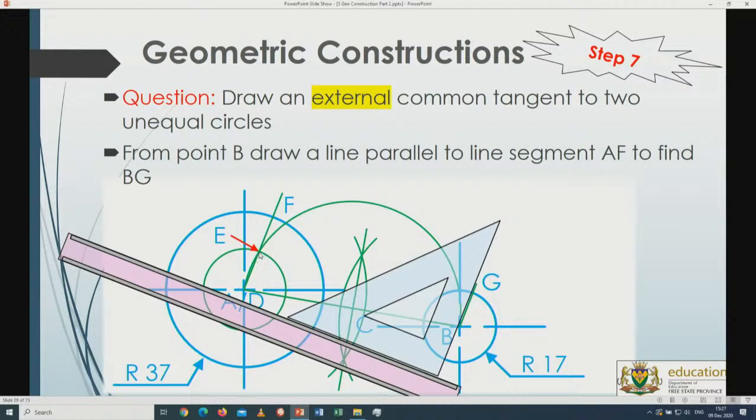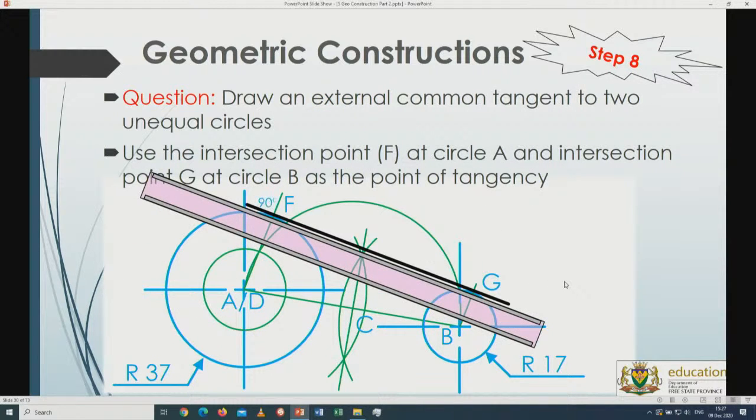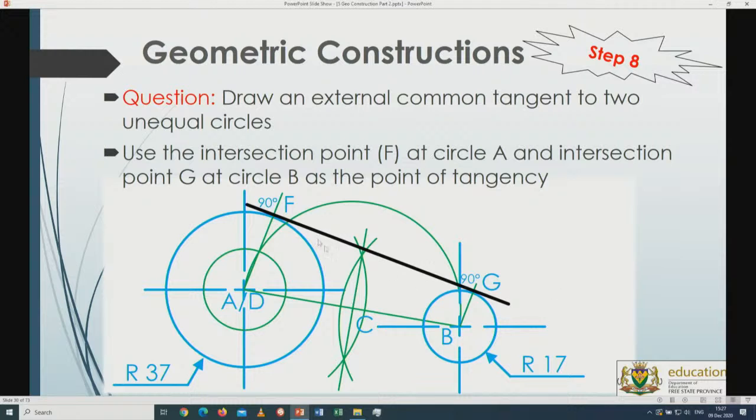I've got the intersection point, extend the intersection point towards the big circle and take it parallel down to the small circle. So once it's there, I can now take my ruler and it will work out perfectly in terms of where this point will be intersecting on that specific point. It will again make 90-degree angles over there, and it will make a 90-degree angle over here from this projection line towards my end result, my answer over here. And that's what you will get.